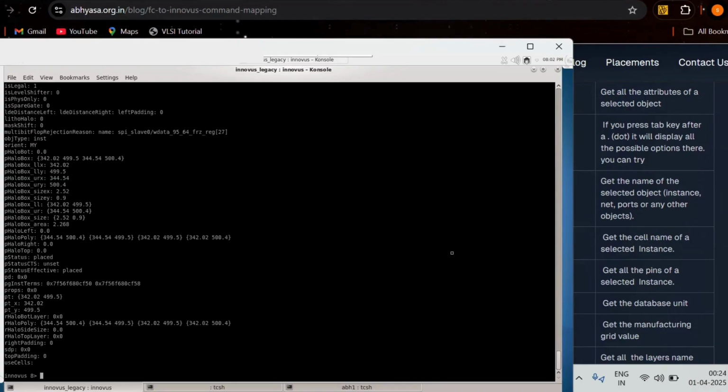If you want to scriptify this, you can simply redirect it to a file. This is the command to redirect, and you give the file name, like inst_attr.rpt. Your command can be a Tcl command or a tool dbget command. You can just give it here, and you need to put the command in curly braces. This would redirect the command output to a file.